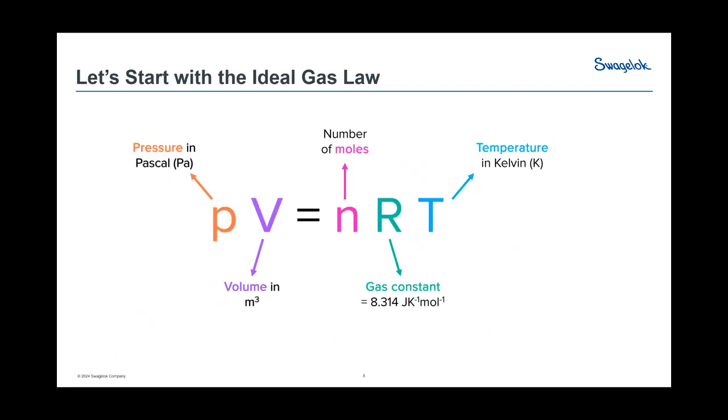Well, there's a problem with that. And the problem is in hydrogen, we don't really need to do that. Hydrogen velocities can go all the way up until they go sonic, in all honesty. And at sonic, we start to choke the flow. The only other time you would be careful on your velocity would be if you are getting an acoustic resonance in your piping or your tubing, that it starts to bounce and you'll see the movement. But beyond that, we can really go as fast as we need to because we are talking very high purity gas with very, very low mass. So erosional velocity doesn't really exist. And that's been seen by many of the experts in the world for years and years and years.